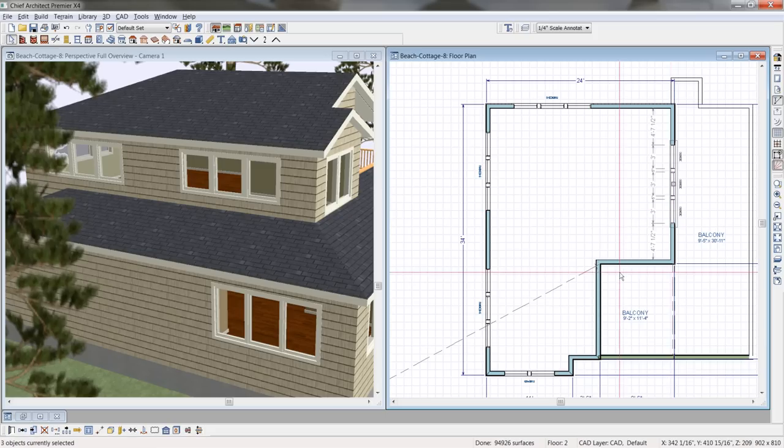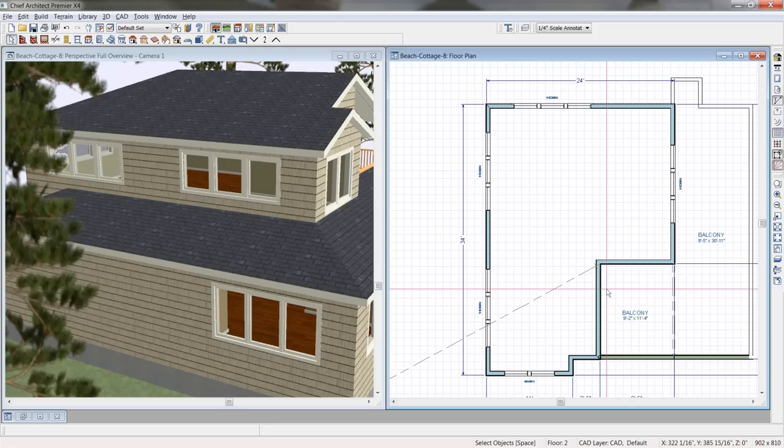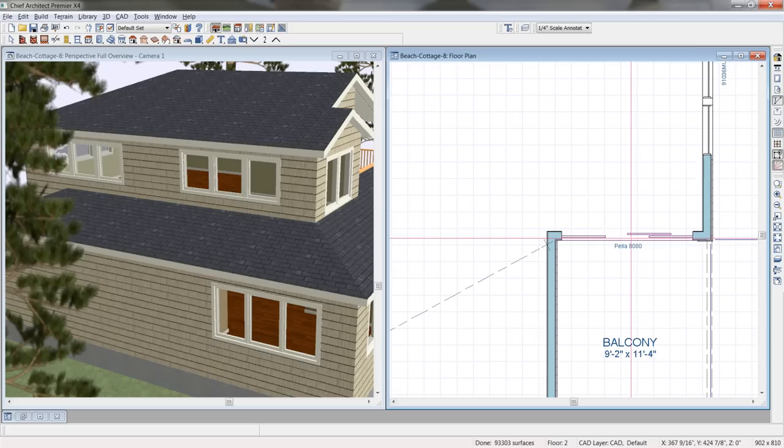But when you mull your windows, again, the advantage there is it's going to create a single opening when we do our framing. I'm going to go down to the main floor here real quick. I'm going to grab this particular sliding door that we have for the back of the house, copy it. I hit the Control-C button, and then I'm going to paste that, and you'll notice I get a snap indicator. I'm going to paste that on the wall up here.